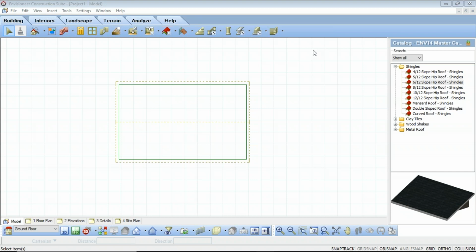So today we're going to be looking at roof framing. Once a roof surface is inserted on a model, you can add framing information to it. The roof can include hand-framed roof rafter framing members, truss profiles, or timber frame trusses. The topics that we're going to talk about today are how to add and modify the roof rafter framing elements associated to a roof, how to insert the truss profile runs, and then how to insert timber frame trusses for a selected area or as individual insertion.